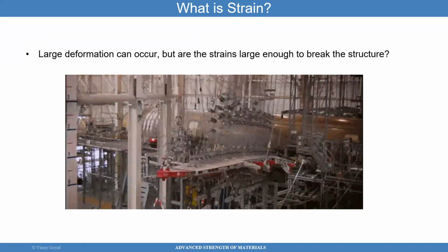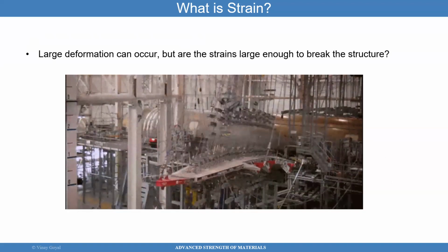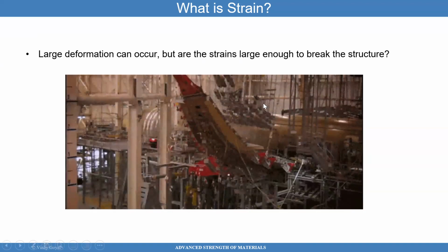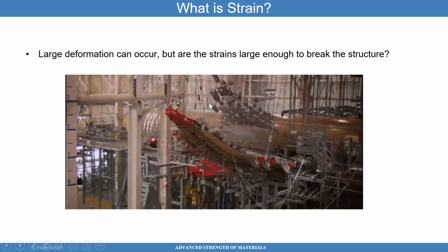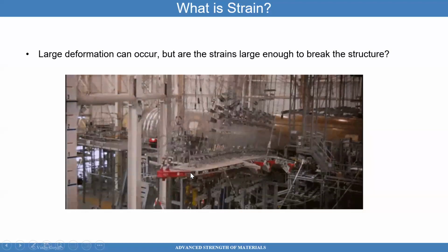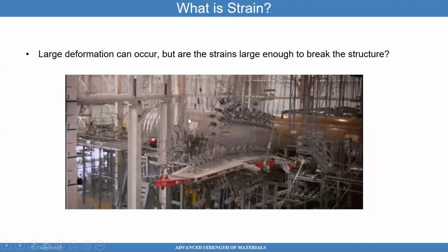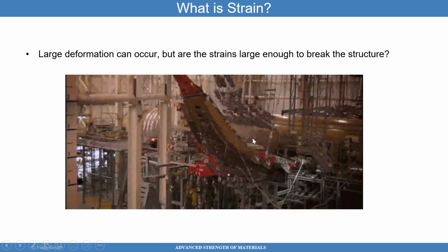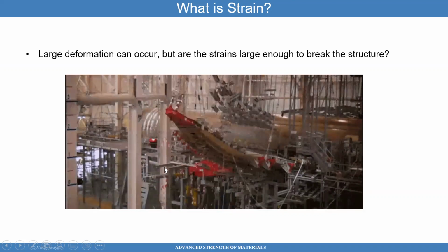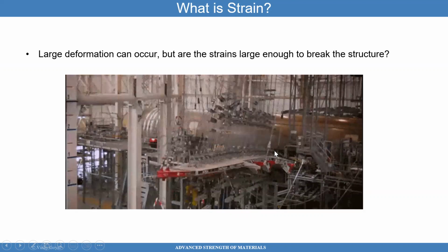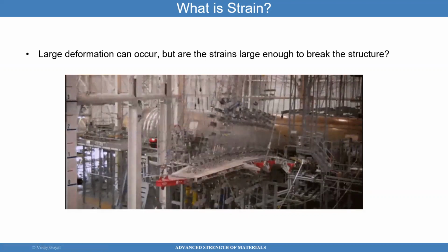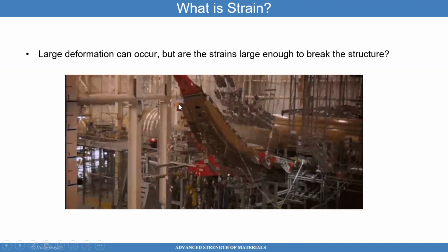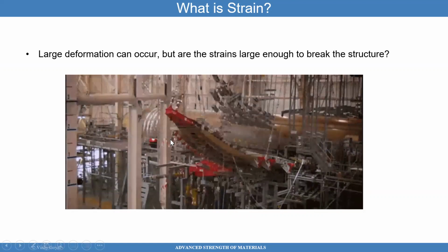Let me show you this picture here. This is a test of a Boeing aircraft, which has attachments that try to simulate the loading environments that this wing is going to see in service. Each of these straps applies loads in a non-uniform way across the wing to best replicate the environments it's going to see in service. As you can see, this particular tip is moving quite a bit. It can move upwards of 30 feet.